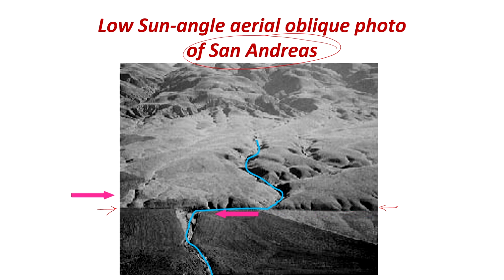Okay. Let us go ahead and see what we also did in India related to the mapping of the surface morphology. This was way back, almost more than 20 years, after the earthquake of 2001, which was triggered in the Kutch region of Gujarat. Initially we identified a couple of faults based on satellite photo interpretation, but later, because there was an earthquake, we also planned to do an aerial survey.